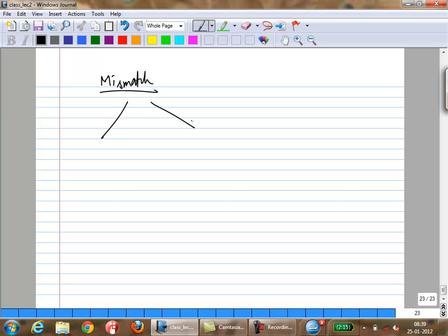So what this means is, let's say if you have a circuit, you want two particular components to be identical or you want them to be exact multiples of each other. One of these two, right? There are many cases. We looked at the differential pair, you want RD1 to be same as RD2, you want M1 to be same as M2. All our analysis is based on that, right?